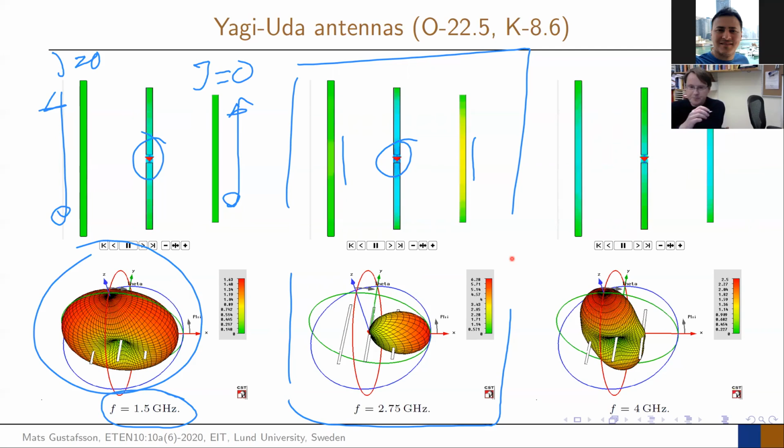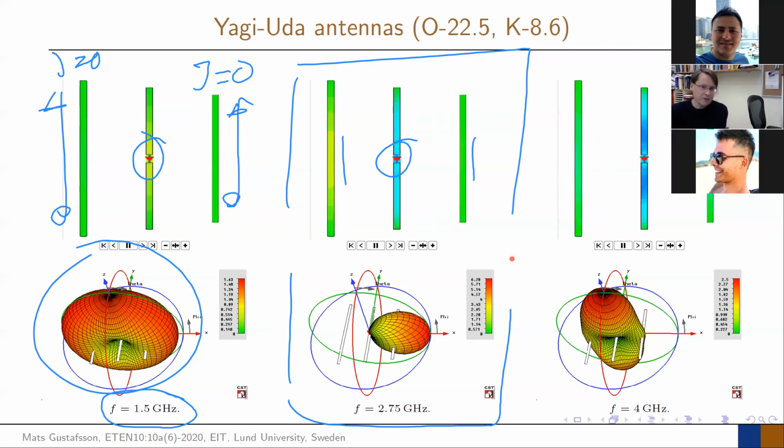It is typically like we have a dipole, because since you don't induce those ones, they don't radiate. You get the radiation only from the element in the center. This is a case where it doesn't work as an antenna. It's not working as the Yagi-Uda antenna should work. It works like a dipole type antenna, so this is not what it's designed for.